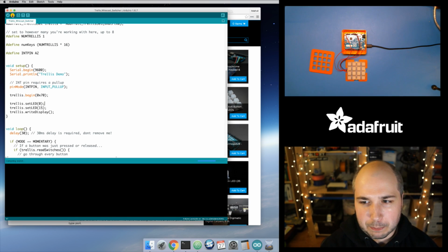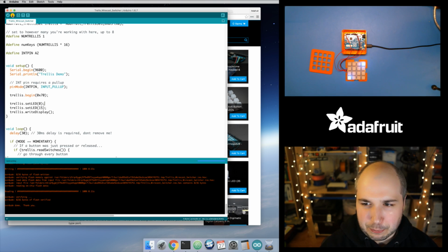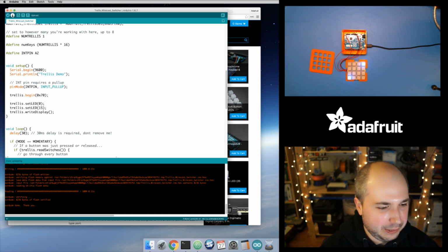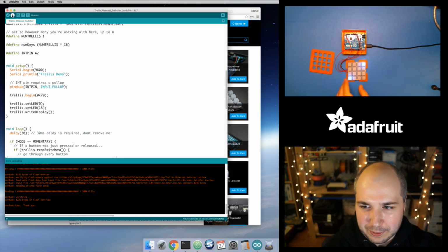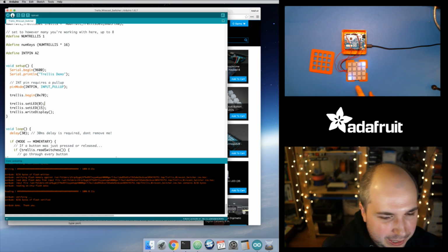And the reason I'm resetting the board is because I'm running OS X El Capitan, and it's got this weird quirk with USB devices where you basically need to reset the Arduino or else it gets confused and it can't do the automatic upload. I don't know if it's a bug on the Apple side or maybe something that we need to learn to deal with. But okay, so this is cool.